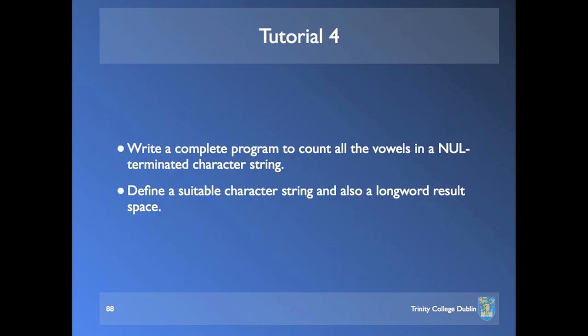And by going back to the argument or the discussion we just had there, we don't have to worry about overflow at all. So all we have to do now is just simply say add.l d4 into d2, add.l d5 into d2, and that's it, finished. Okay?